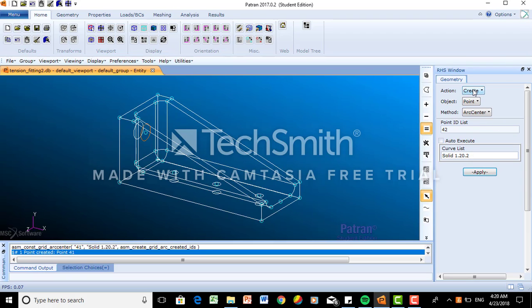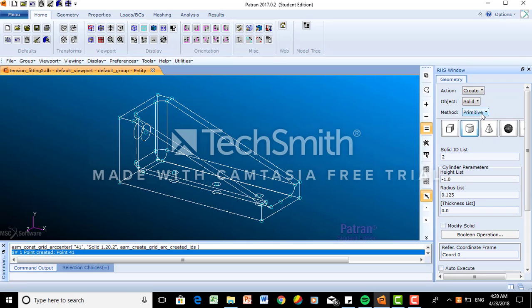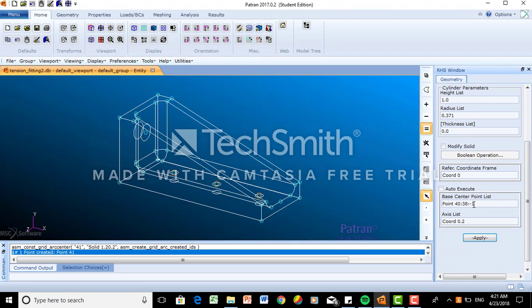Now we're going to make sure that Create, Solid and Primitive are selected in Geometry. Now we have to select the cylinder icon. Enter 1.0 for height list and 0.371 for radius list. Now click on the point in the center of the large hole. Make sure to turn Auto Execute off. And enter 0, 0, 1 for axis list. Then click Apply. Select the smooth shaded icon.